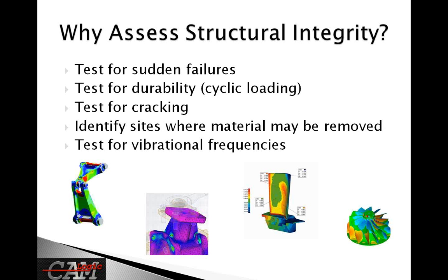The last area is that of vibrational analysis, looking and testing for vibrational frequencies. If you know what the vibrational frequencies of the component might be, then you can compare those frequencies with the frequencies that the overall product is going to experience.